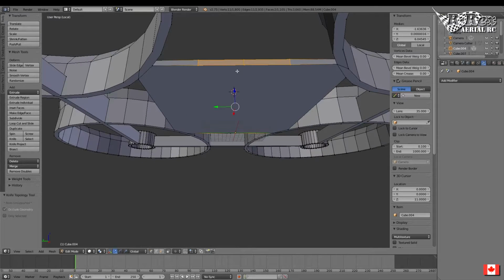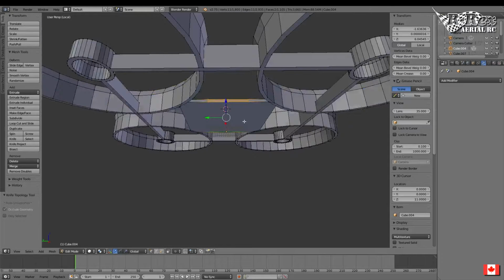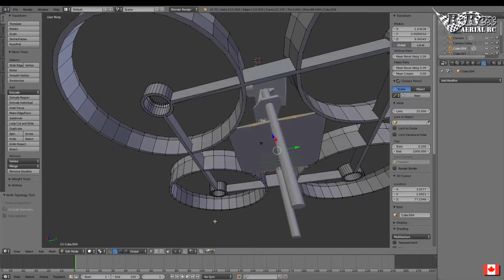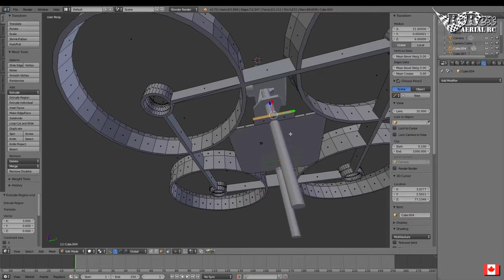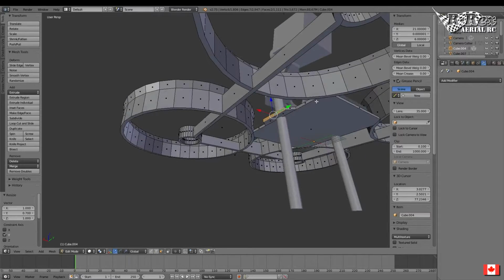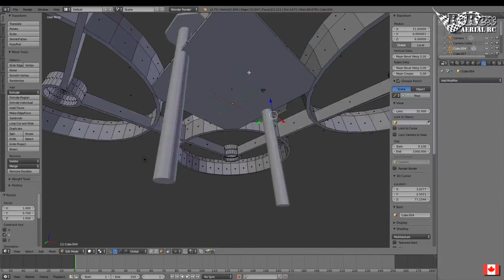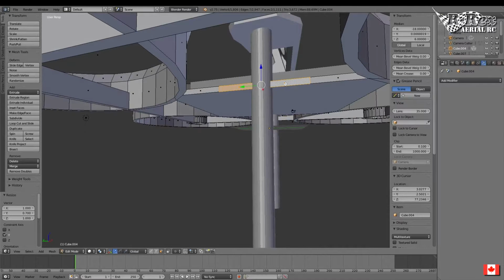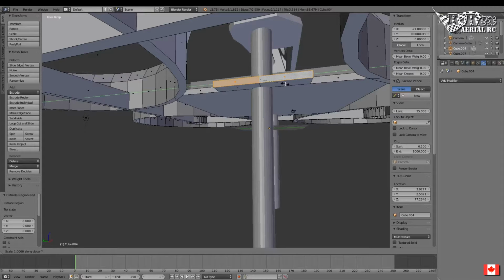Okay, now I'm going to go out of the isolation mode, select the faces, and extrude, let's say, 3. Now I can scale, nope, I want Y. Let's go 0.7. There we go. Extruded 3, scaled on Y, 0.7. Same thing here. Extrude 3, enter, scale, Y, 0.7.